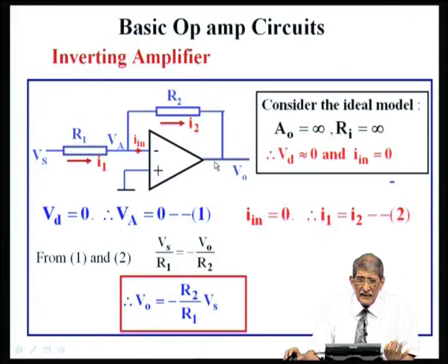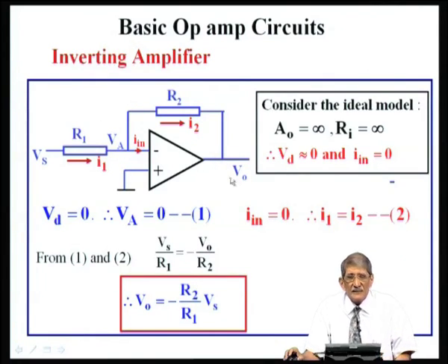One has to ensure that the power supply voltage is more than 5 volts. If the power supply voltage is 3 volts, the output voltage is saturated at 3 volts. So, you will have clipping. Okay, this is the inverting amplifier.